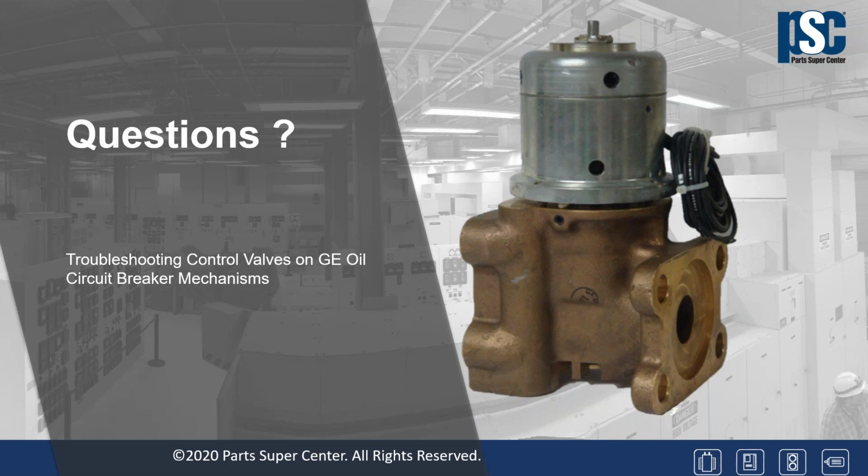What they've done is they have taken out the spring, that is the pilot armature bias spring, and they've made that solid. And then they've gone ahead and reassembled the top cap on the pilot on the valve housing and continued to turn it using the spanner wrench in an attempt to recoin that seat. So folks have indicated that they've had varying degrees of success. I've actually never been able to do it.